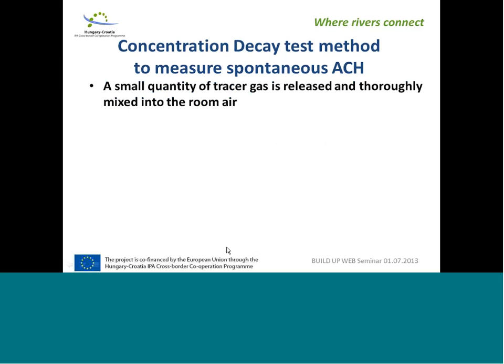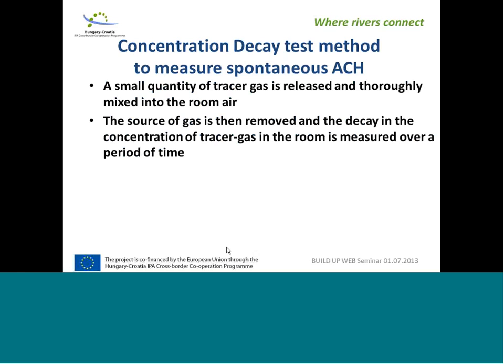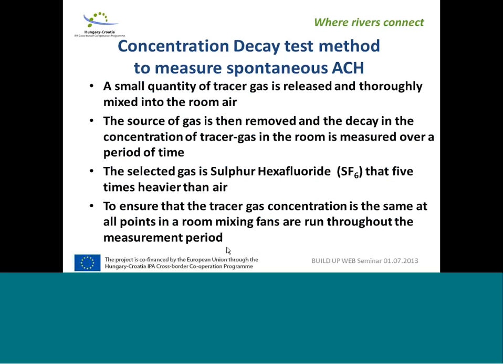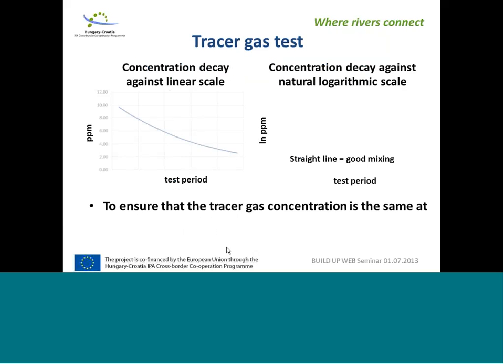We selected the concentration decay test method using SF6 tracer gas. We release a small quantity of tracer gas in the air and measure the concentration decay. Since sulfur hexafluoride is 5 times heavier than air, a proper mixing fan process should be applied during the test to ensure that the concentration is the same at all points in the rooms. So the